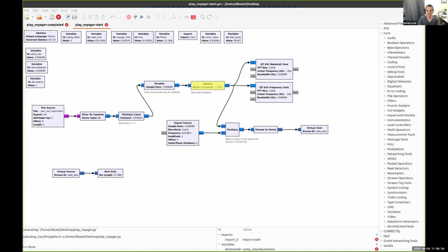Yeah. I guess the difference that we'll see in this plot is that the waterfall sync and frequency sync that we were just viewing, we're only doing an FFT size of 1024. And what we'll do in the integration is 32,000. So we get much finer bins, so they'll be less noisy in that way. And I don't know how many integrations the frequency sync was doing there when I turned on high averaging, but it's probably less than 100.